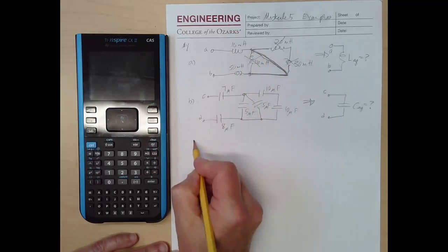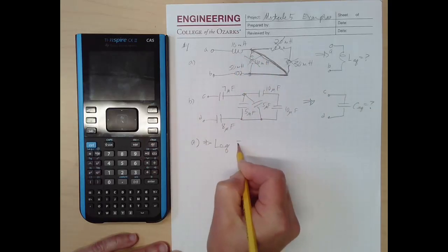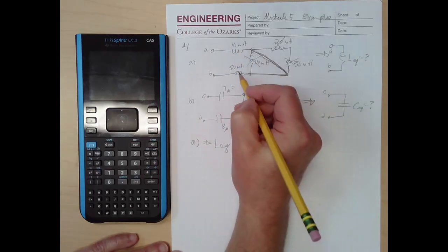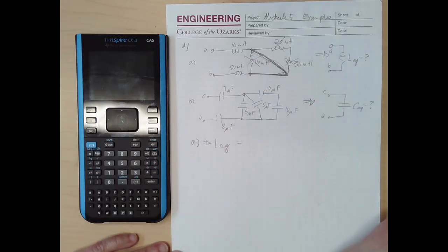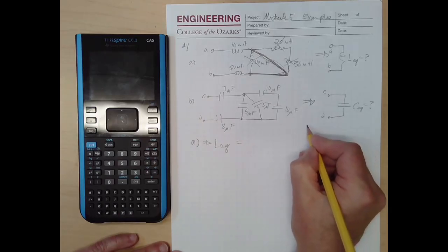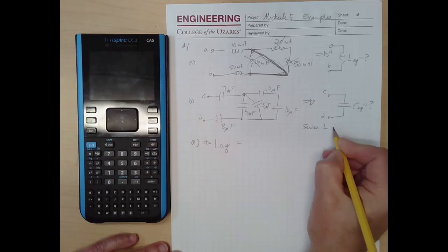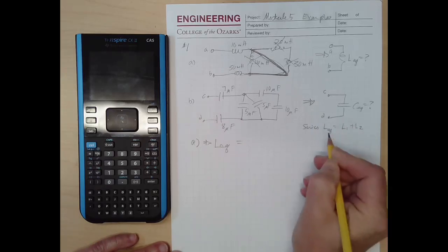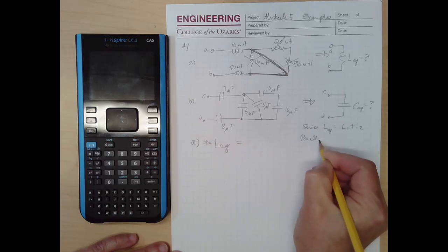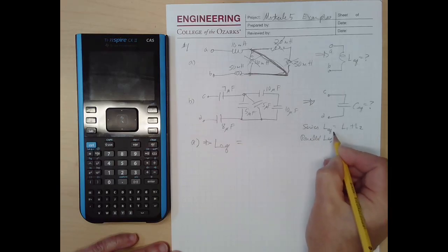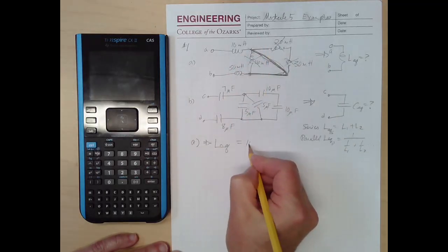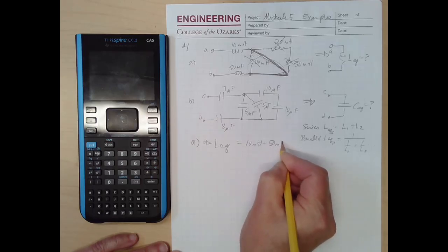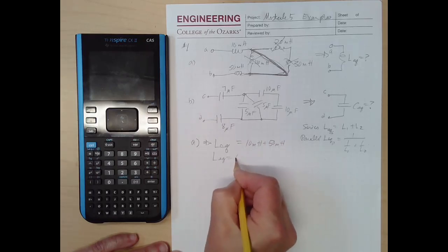So for this circuit, kind of a trick circuit, for part A, L equivalent is what? Well, we have 10 millihenries in series with 50 millihenries. Hopefully you can see that, right? And this comes right in here. This is like one node. And so how do we combine inductors in series? Remember, for series, L equivalent is just L1 plus L2, just like resistors. For parallel, L equivalent is 1 over L1 plus 1 over L2, and so forth. So in this case, all we need to do is 10 millihenries plus 50 millihenries, because they're in series, and so L equivalent is just 60 millihenries for A.